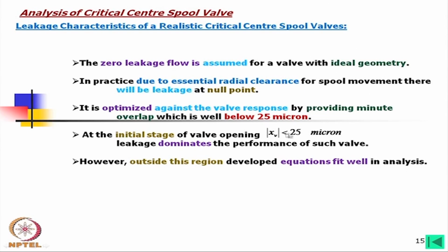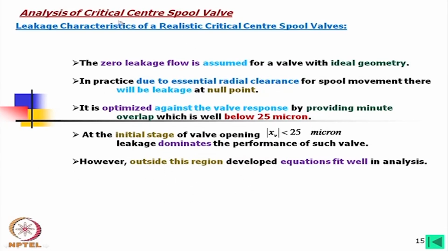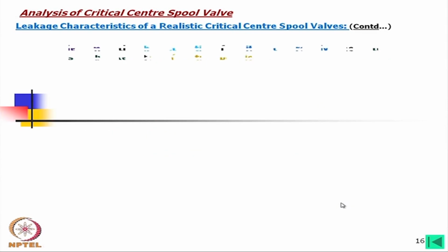So, suppose we take another position where, say, 15 liter flow is there and we have to control over that, then it is not difficult. Even then, it will not matter whether the valve is critical center, open center or closed center. But still critical center is widely used because the motor is usually driven for both directions. This is important. We have taken this one as an example.